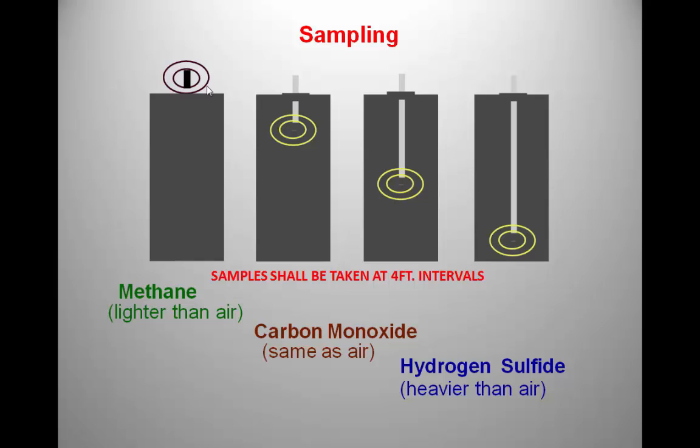And if you drop it down into bad air, say to the bottom of the space, it goes into alarm. By the time we pull it back up and it comes to good air, we may not see that reading. A lot of times the monitor will not reset itself. You have to manually acknowledge it, but you still won't be able to tell exactly what area that alarm went off in. So that's why we don't just lower the monitor. That's why we use our tube and our pump.